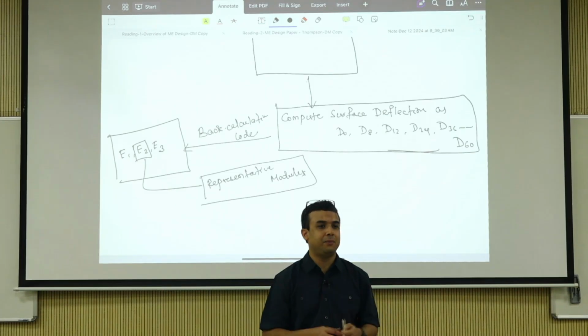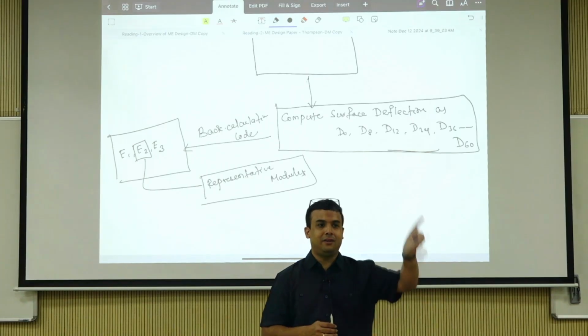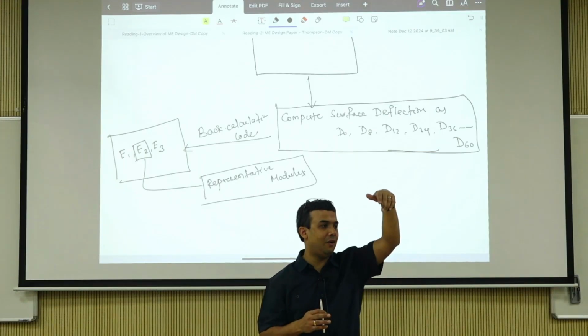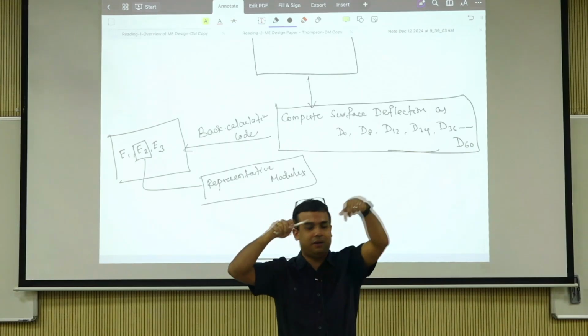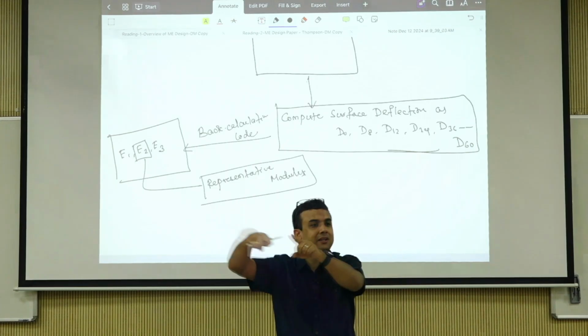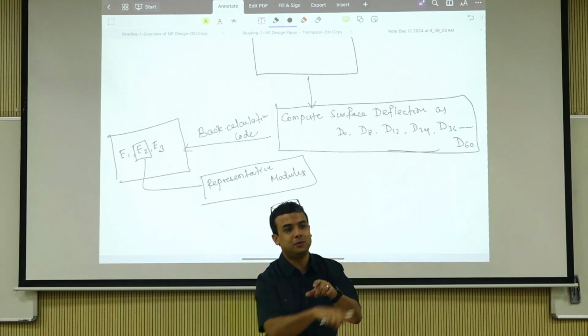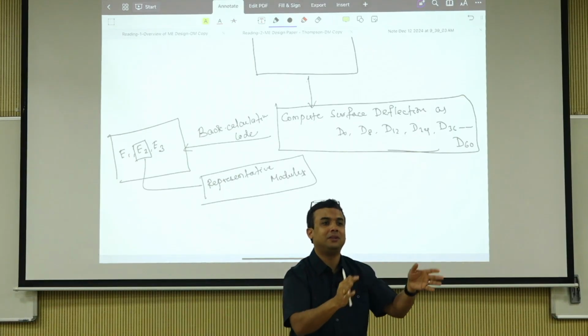You can write an FEM code and you just say that this is my test result. Apply a 9-kip load or half of an E cell onto the surface. Calculate the D0s and everything, feed into the FEM, calculate the D0s, automatically feed into the back calculation, automatically do like a scalar and stuff like that, and now find out E1, E2, E3.